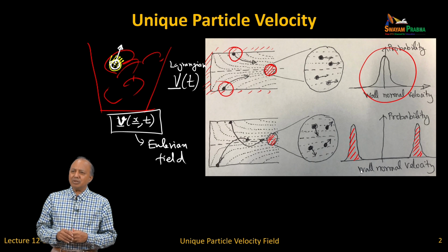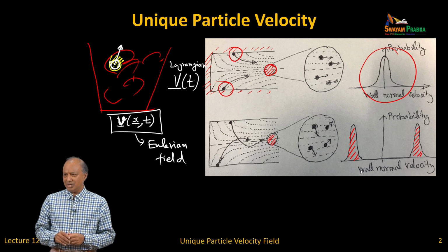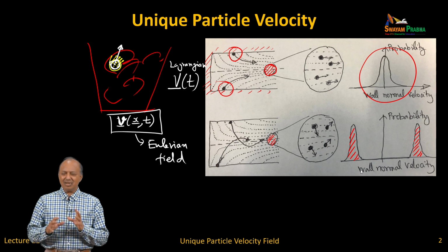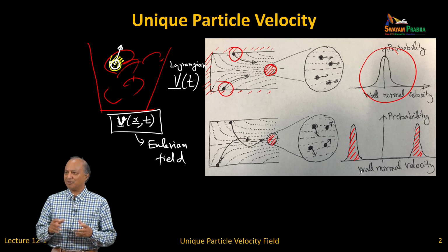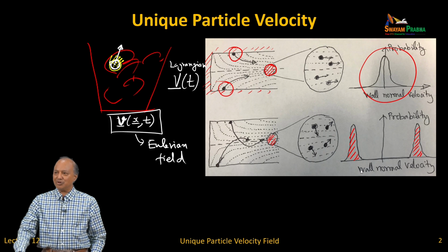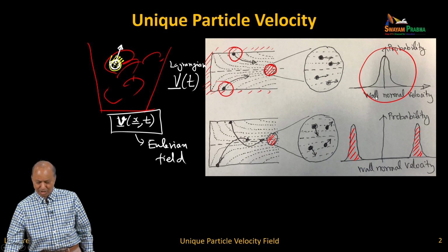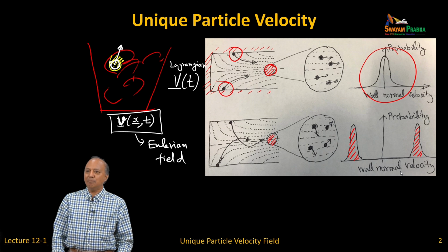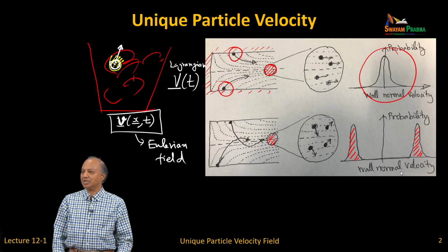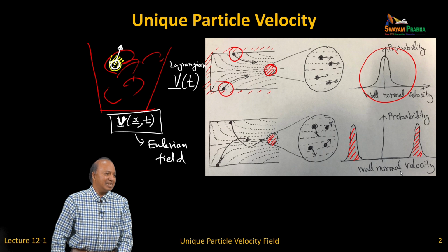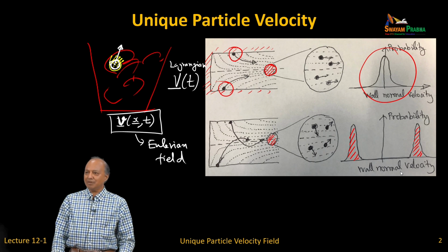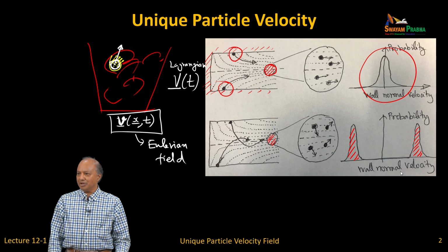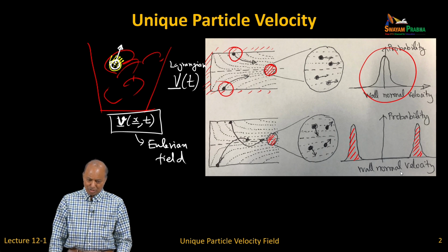If the Stokes number is very large, Euler is in little shaky territory. I mean, whatever you compute is based on a scenario like I show here. An Euler-Lagrange method is typically better because it's able to track the fact that your particles are remembering where they get injected and so on and so forth. This is something for you to remember. In some problems where there is a lot of particle memory, the Stokes number is large,